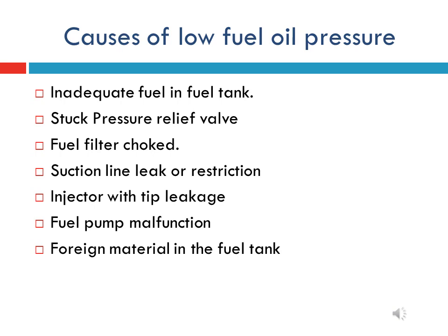Seventh and last is foreign material in the fuel tank. If foreign materials are in the fuel tank, the suction pipeline may get choked up, so at that time also we will get low fuel oil pressure.